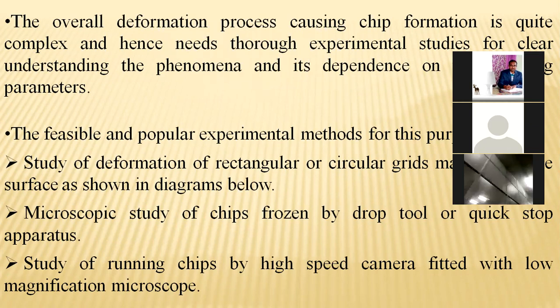coming to the feasible, in order to eradicate this, for example in the case of wet conditions, nothing but lubrication. If you apply the lubrication, the temperature stresses at the point of contact of the tool and material will decrease. So by this we come to an acknowledgement that high feed rates and speed rates can be progressed either in the turning machine or milling machine or drilling machine, whatever the machining process may be.